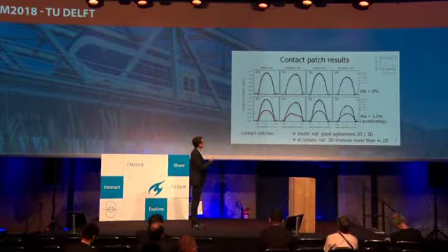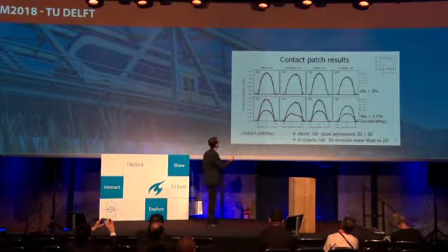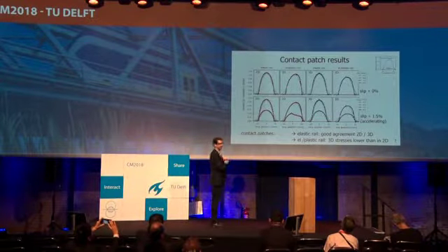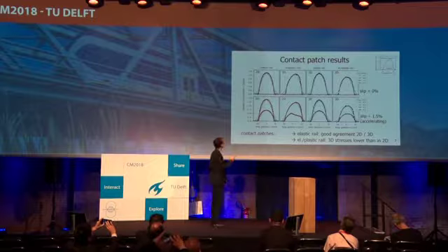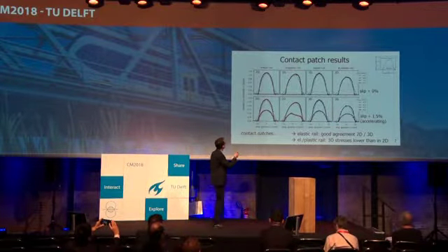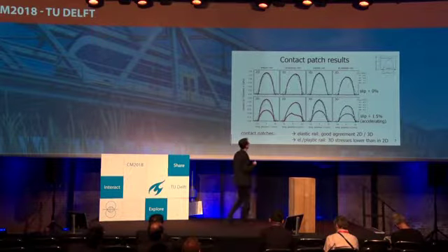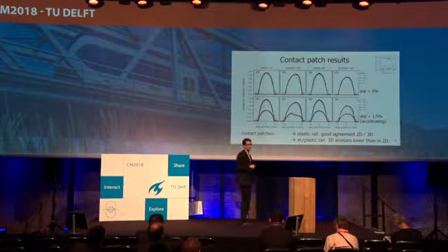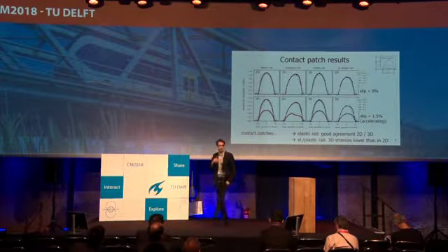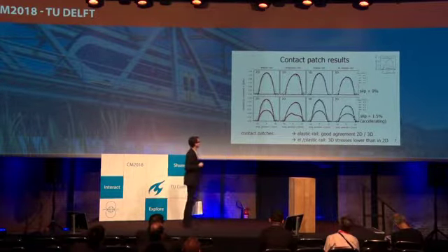Okay, now let's start looking at the contact patches. Here we have the results for a slip of 0%. We set up the 2D model to have the same contact patches in the elastic case with the Hertzian formulas. We see that fits pretty well. If we introduce elastic plastic material properties of the rail, we see that our contact patch is a little bit unsymmetrical for our first time when we roll over the plastic rail.